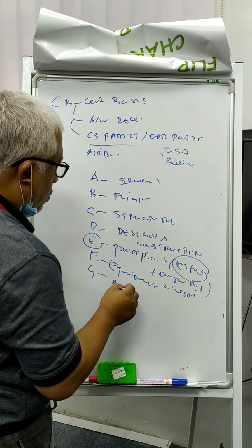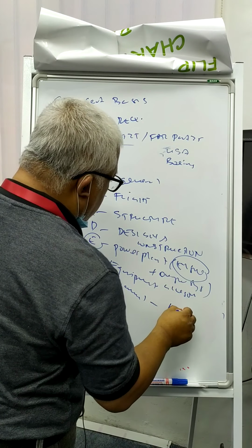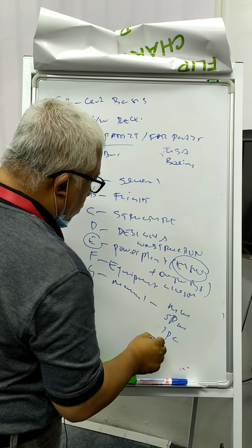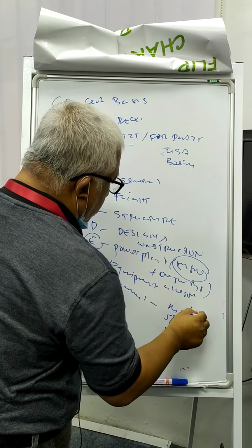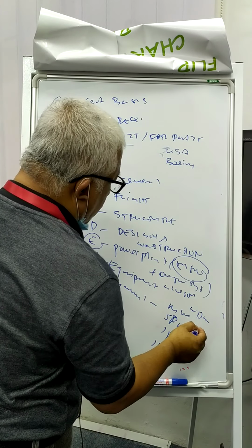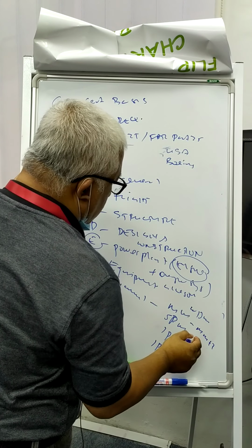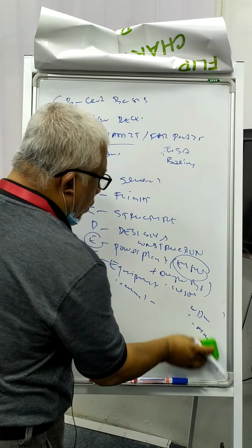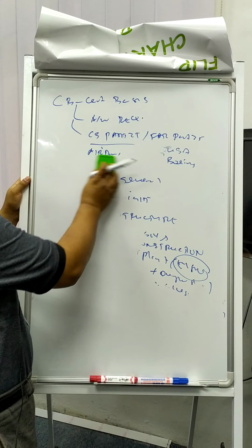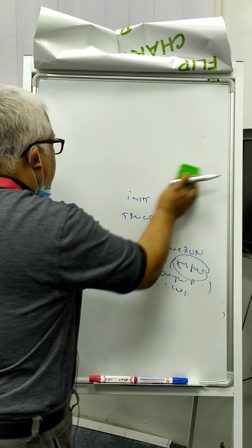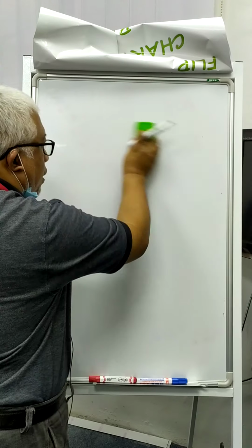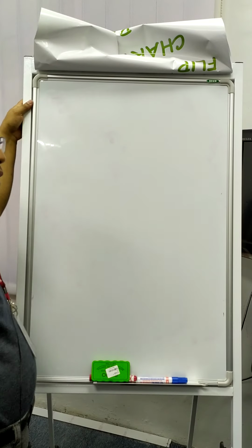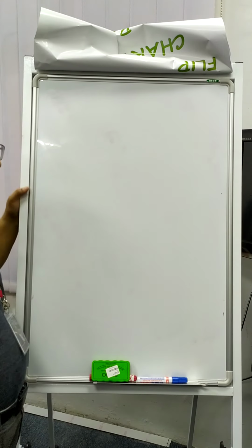G is manual: all the maintenance manual, structure repair manual, illustrated part breakdown catalog, wiring diagram manual, MMEL, MPD. Everything is under subpart G. That's why we have those manuals. It's not just because the OEM wanted to publish them for you, but they have to publish them because they need to satisfy subpart G in order to certify the aircraft. So as the aircraft got damaged, the COA is no longer valid.